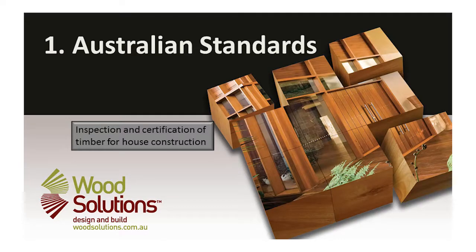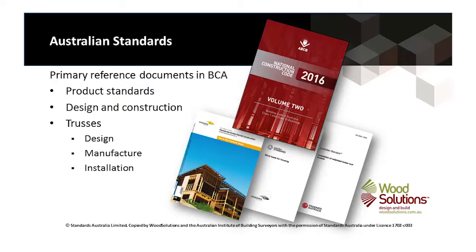Module number 1 is Australian standards. When we say timber complies, it complies with the National Construction Code, and the National Construction Code is the document that puts together acceptable construction and design manuals, and these are the compliance documents that we're using. So they're primary reference documents in the BCA. They include product standards, they include design standards, they include installation and construction standards, and then trusses have a suite of standards that they look at themselves.